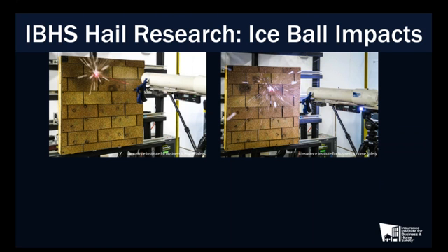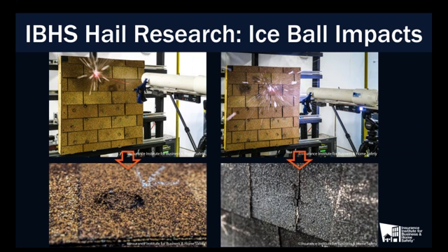So it kind of gives a nice view of what this looks like. And these are the kind of damage patterns that we were able to produce in that study. A lot more granule loss as opposed to crushing those granules, which is definitely more representative of what you'd see on an actual house. You'd still get sometimes the denting, the cracking, the tearing that we saw with the UL test, but the behavior of those granules is what was really encouraging.